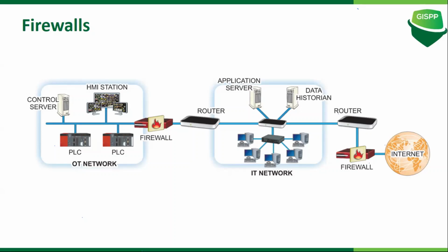So while implementing OT security, we have to see availability as the first aspect. We will not see confidentiality as the first aspect. That is the most important concept. If we go from IT security to OT security, the thing that we have to install in our mind is that we have to think from the availability aspect.